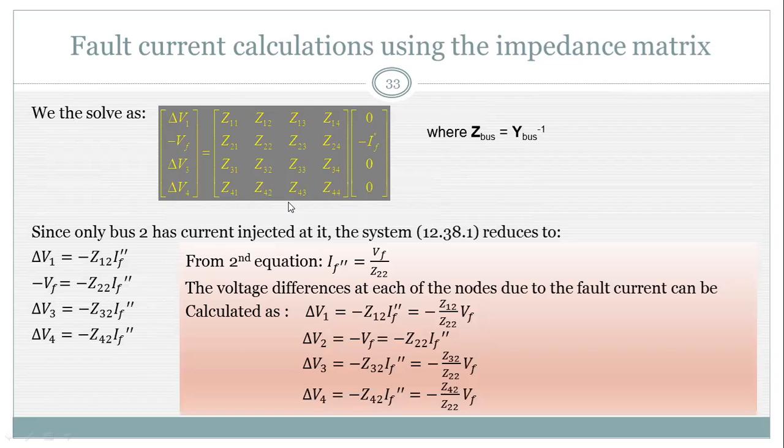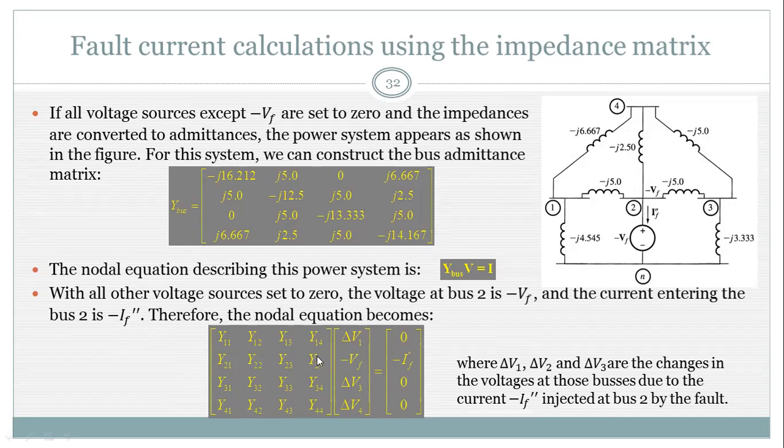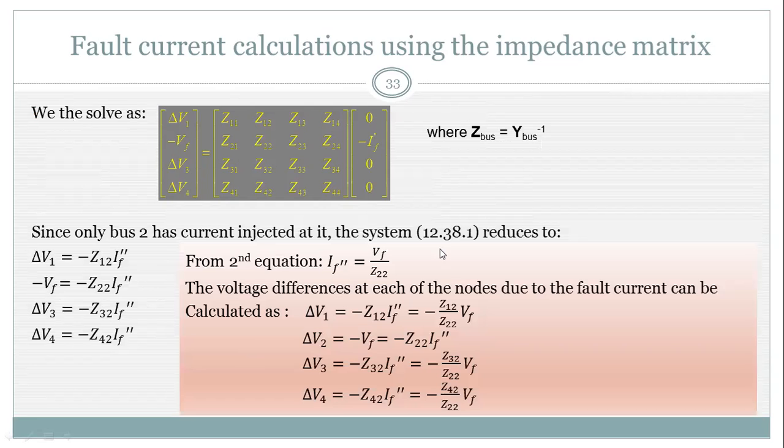So now if we want to calculate the bus voltage change at the instant of initiating fault, then this bus voltage change should be on the left side of the equation, and all other things on the right side. Whenever we want to shift the admittance matrix to the right side, this admittance matrix should be inverted. The inverse of the admittance matrix is called the impedance matrix. So what is the impedance matrix, or the Z-bus matrix? The impedance matrix means the inverse of the Y-bus matrix.